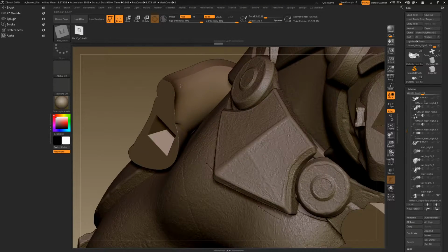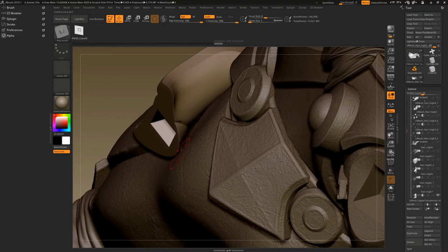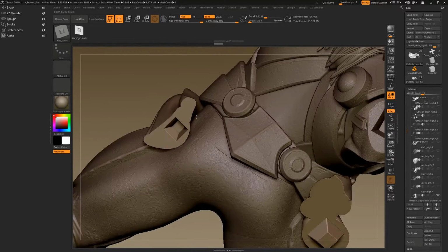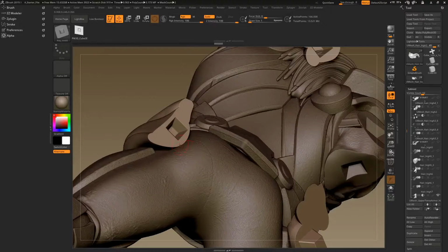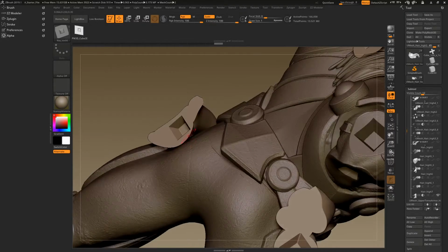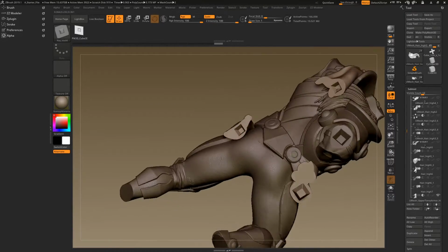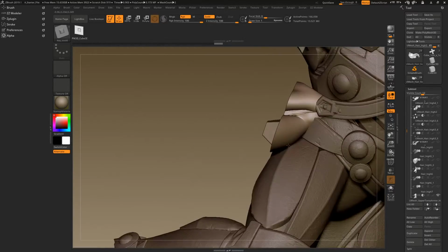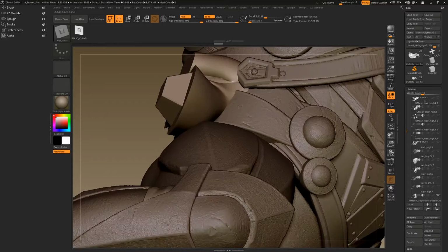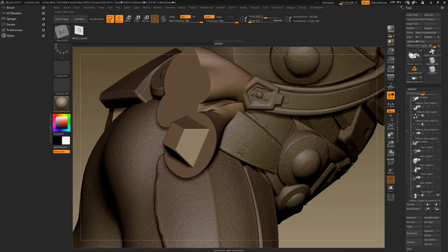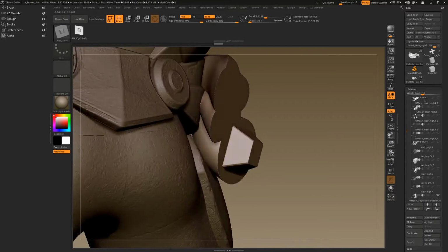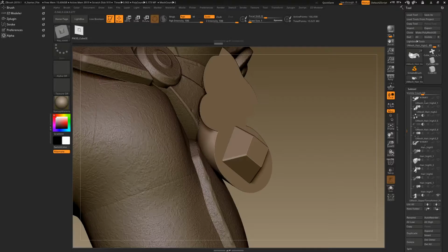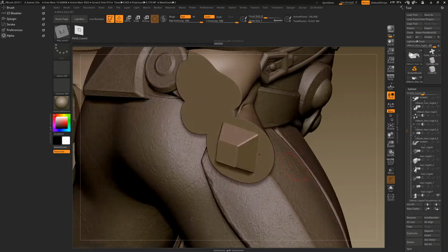If we were molding and casting this, I'd want to bring this into alignment of draft, and I may still do that just to make it more stable. It just means pulling the geometry into the body to make that blend off a little bit better. Again, I'm making minor corrections to Spicer's model. Again, nothing too ridiculous. I'm also noticing that this is interpenetrating the clasp. So again, I'm going to make that change for him to clean it up. So those are my 3 things I've got to pay attention to.